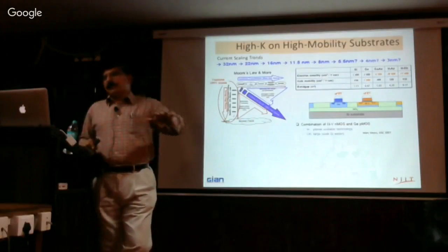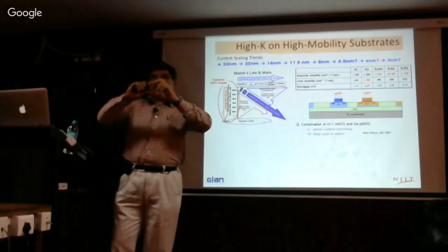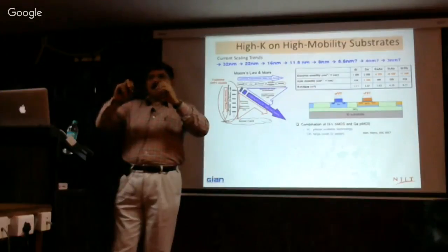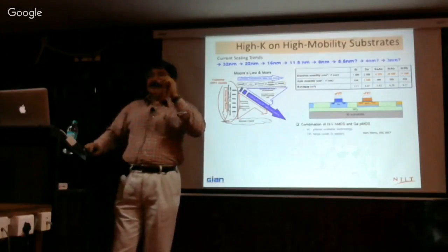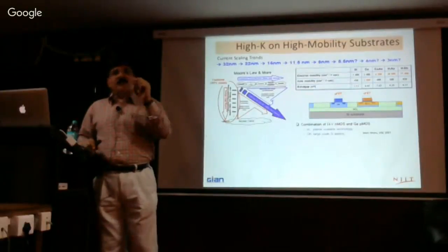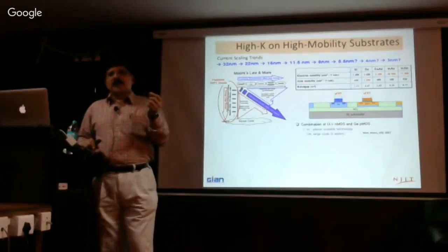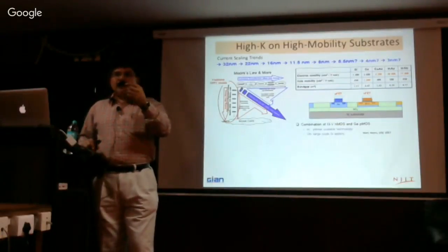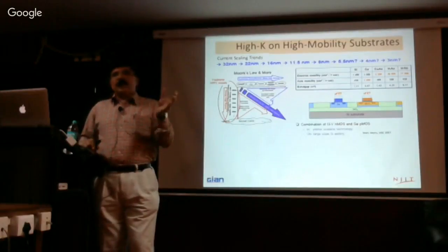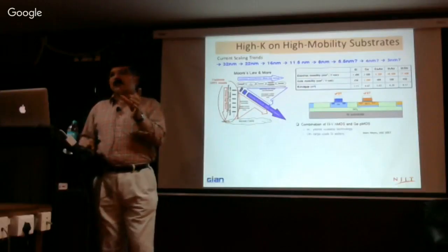So many different chips are there, but they are still packaged separately, even though they are flip chip packaged, because the chip that communicates with the outside world is not silicon. That is gallium arsenide, or indium gallium arsenide, depending on the company and the quality they have got. Now the trend is that it can be integrated into the silicon base.